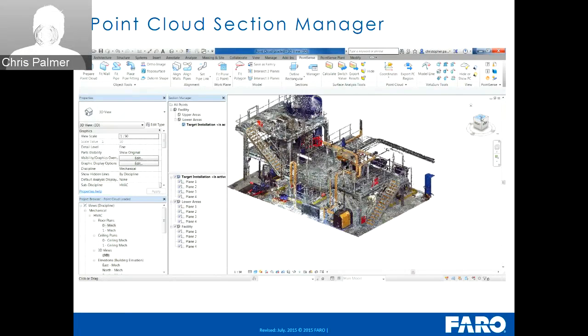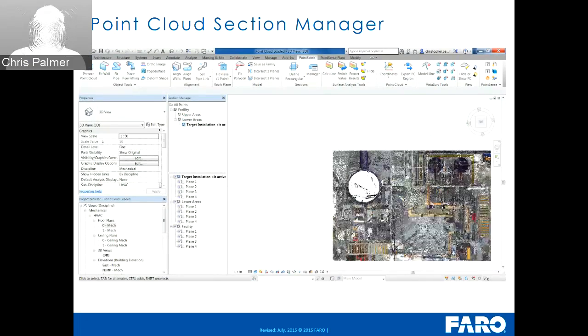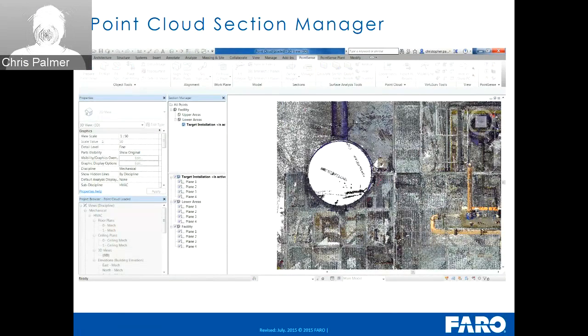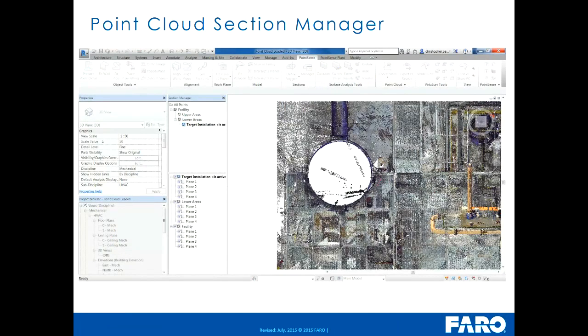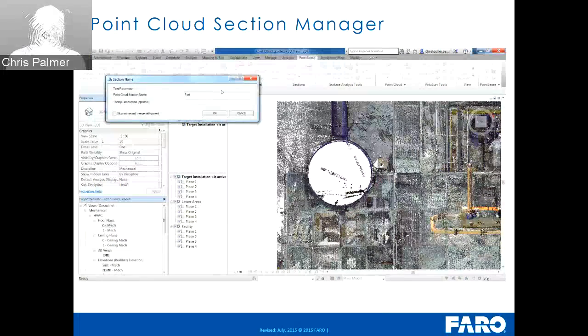So I'll just drop this into a top view and zoom in a little bit. If we want to maybe isolate a specific area, it's sometimes easier to use a polygon selection. So if we go to the Define Polygon tool, I'm just literally going to click around the outside of this now to just define the tank. And as we work our way around, if I just press the escape key, what that's going to do is just isolate out that tank. We just give that a name, so we'll call this tank.